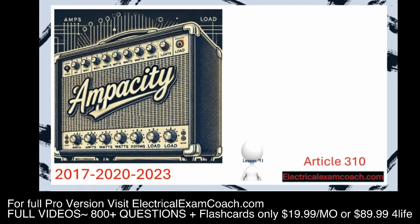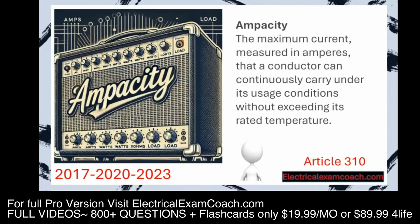We're going to be in Article 310, and we're going to be learning all about ampacity. Ampacity is the maximum current measured in amperes that a conductor can continuously carry under its usage conditions without exceeding its rated temperature. Everything that we're doing in this program and out in the electrical field is to protect first the people and then the equipment. And it's no different with the wire.